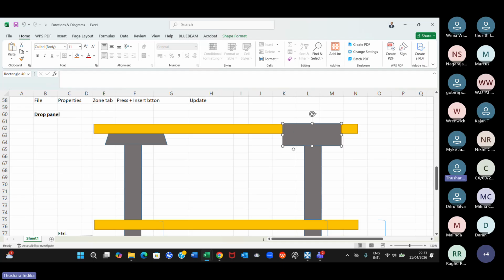Sometimes some people can say it is a flat slab with column pedestals. So column pedestals can be measured separately, either way. Or you can measure this as, let's say, a 600 millimeter thick slab, this portion, and the balance is 225 or 250 millimeter thick slab. So either way it is okay. Sometimes you can measure the entire slab and then the projected part at the bottom can be measured as column pedestals. So people use both methods.